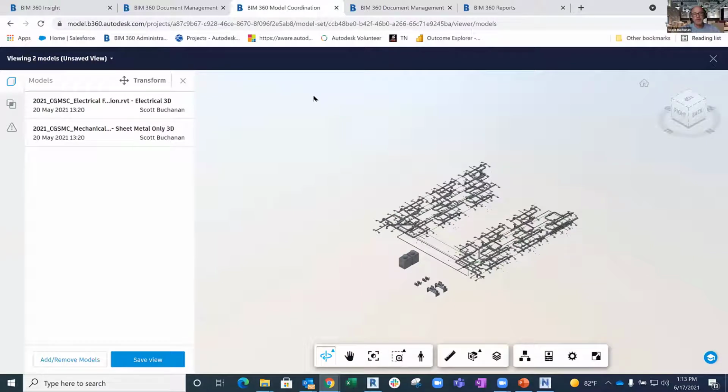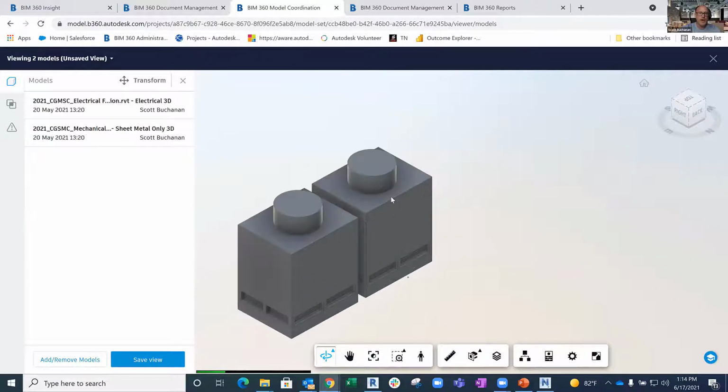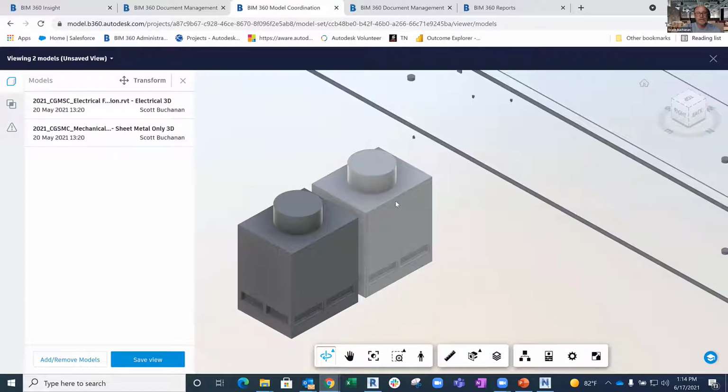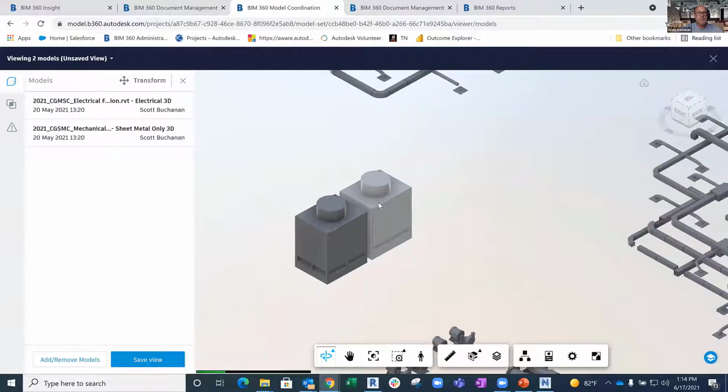The reason for that is it's not on our side; it's how those products write to an IFC file. They don't use the same element ID every single time they create an IFC. For example, if I was using a non-supported product, when it spits out this cooling tower, it may be element ID 12345A. The next time they export an IFC file, that would be rewritten to a completely different number. That causes problems here because we're attaching issues and behavior to a unique identifier. So that's one to keep in mind.